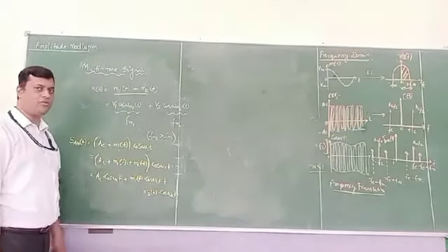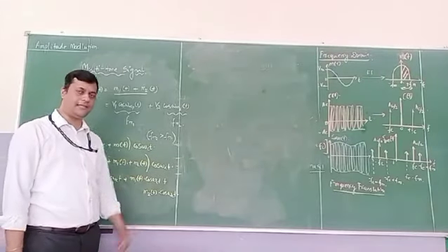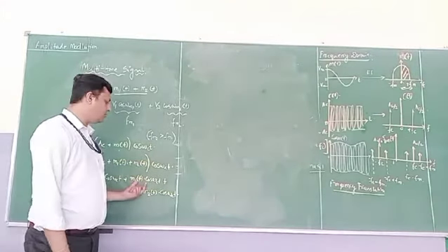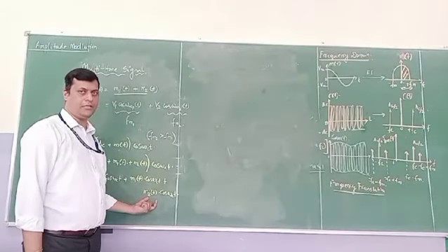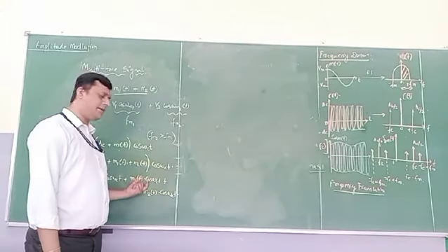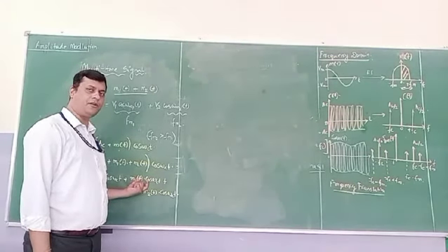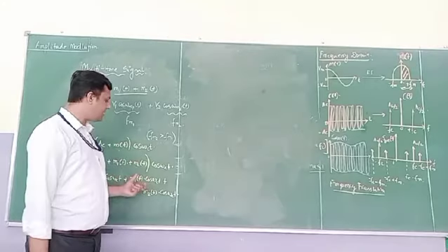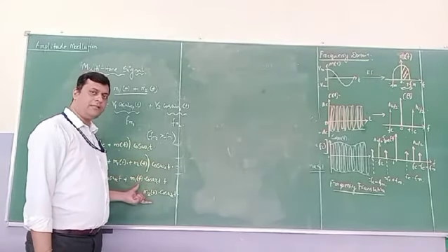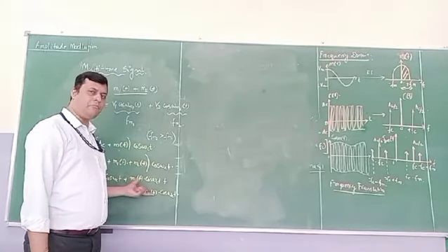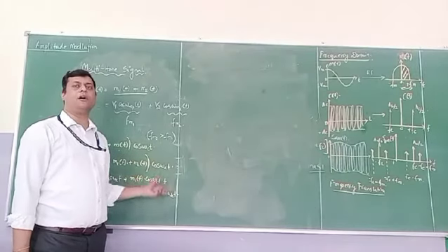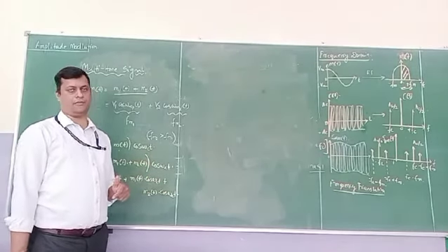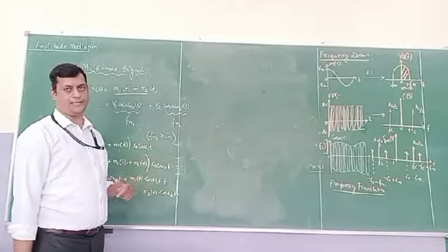So more than one sideband signals are available: two sidebands for m1 and two sidebands for m2. If it is a single tone, the upper sideband and lower sideband correspond to the message component, but here two sets of sidebands are available. So that means two message components are available, and we have to identify the two other frequency components. For that we have to represent it.